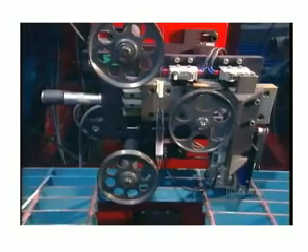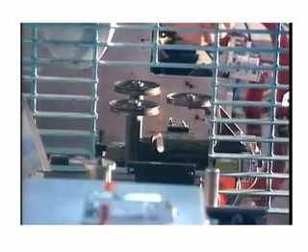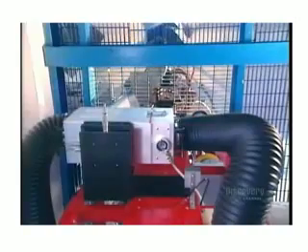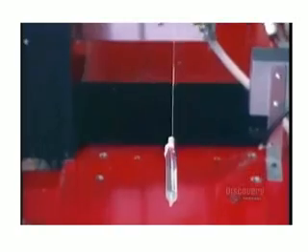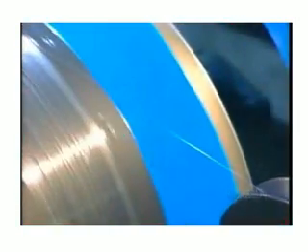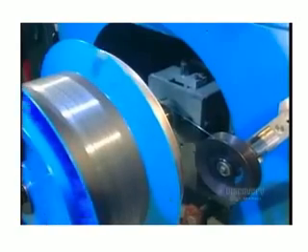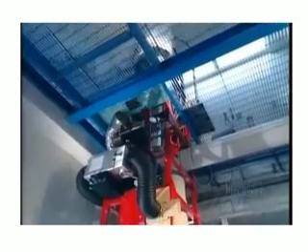A series of pulleys measures the tension on the fiber as it's being drawn. A special monitor makes sure the fiber's precisely the right diameter, 125 micrometers. That's about 1/8 of a millimeter thick. Then the fiber passes through UV lamps that bake on an acrylic coating to protect against dust and other contaminants. Finally, the fiber is rolled onto a drum. From here, it's either shipped out as is or put into a cable.